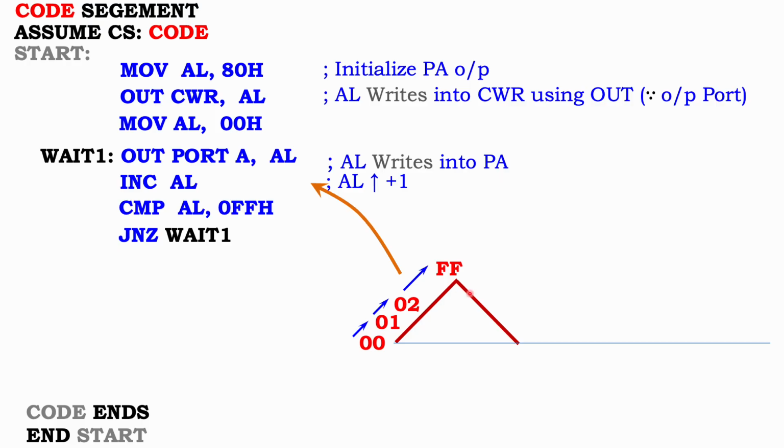To obtain the analog triangular output, we require the fall. See there, the fall from FF to 0. Again it is falling step by step, one step, second step, like that. FF to FE, FE to FD, like that until 0. What happened now? The highest value will be decremented by 1. So we are going to use decrement here.